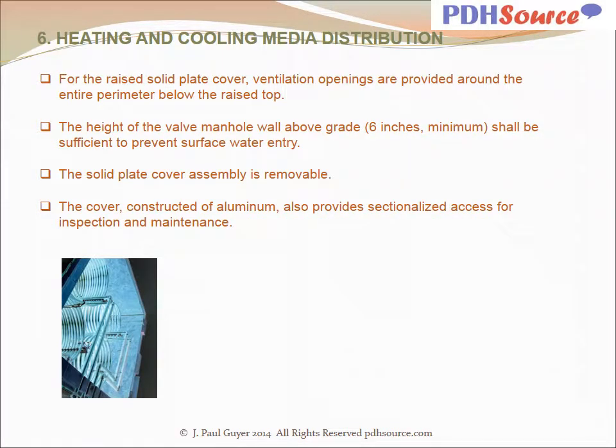For the raised solid plate cover, ventilation openings are provided around the entire perimeter below the raised top. The height of the valve manhole wall above grade, 6 inches minimum, shall be sufficient to prevent surface water entry. The solid plate cover assembly is removable. The cover, constructed of aluminum, also provides sectionalized access for inspection and maintenance.